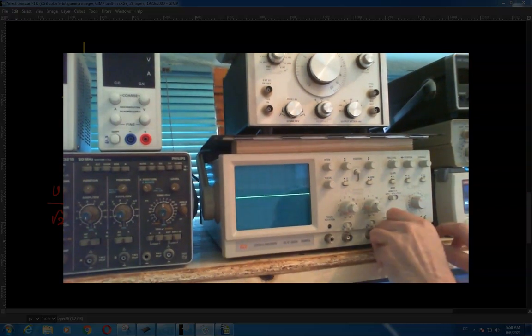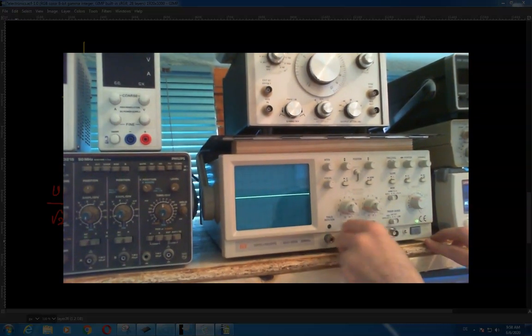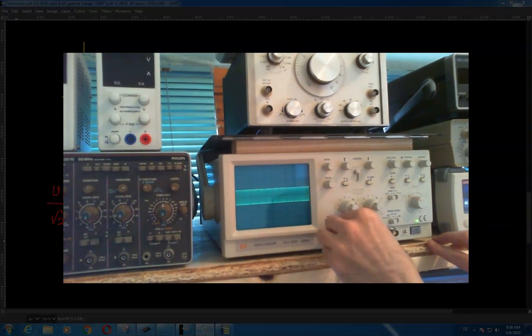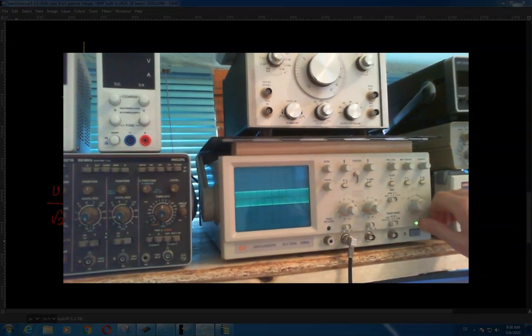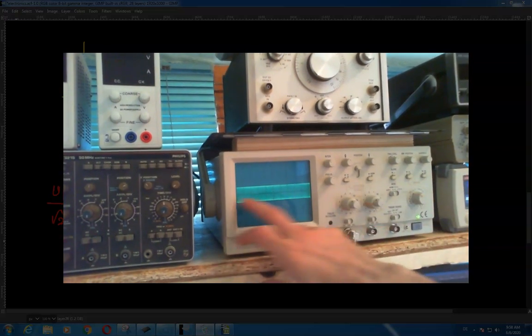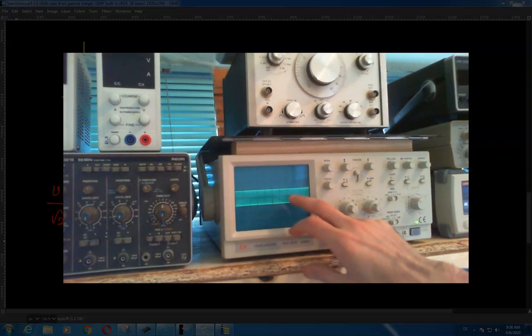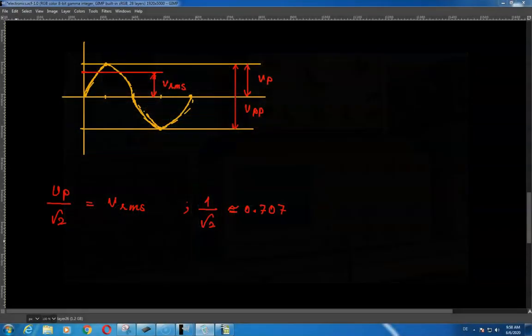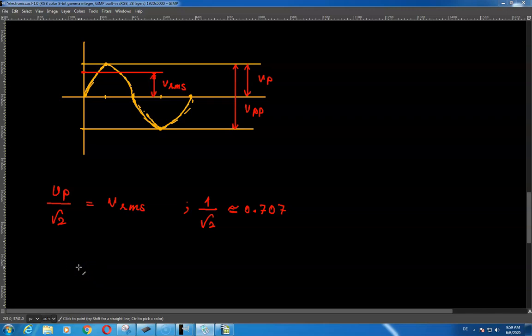I'm going to the trigger actually. You would connect it to channel 1 of your oscilloscope, for example, and make sure that your reference line is ground. Of course, not important right now. Then you would set up your signal in such a way that your frequency becomes 15 kilohertz. So let's see what 15 kilohertz actually means.